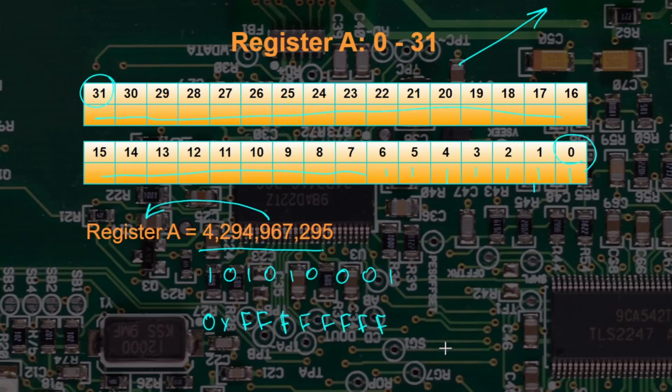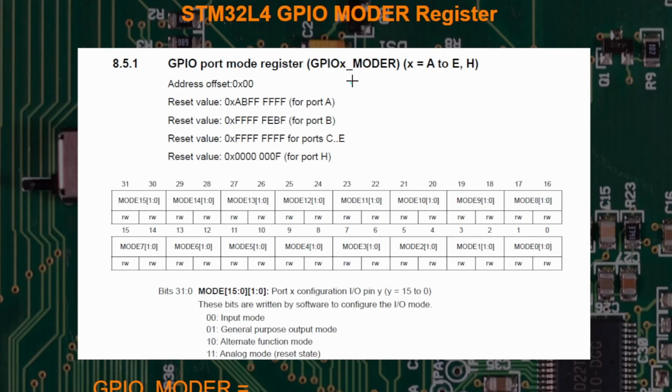Alright, let's move on. What I've got here is a mode register. I actually pulled this from the STM32 L4 reference manual. It's the actual register we'll be programming today. And this register is responsible for setting modes for each pin. As you can see, this is also a 32-bit register, ranging from 0 to 31.